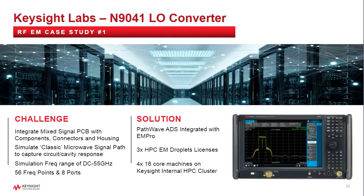The solution that we're going to use is PathWave ADS with EM Pro. For this case study, we used an internal Keysight high-performance cluster that we have in Ghent, Belgium. We only have 4 nodes on that cluster, so we're going to parallelize this out to 4 parallel frequency sweeps.